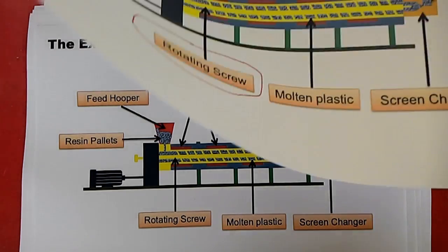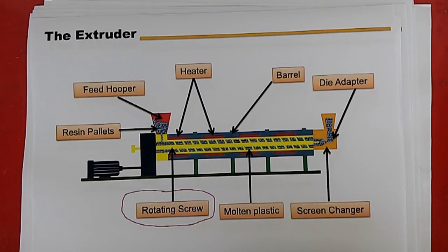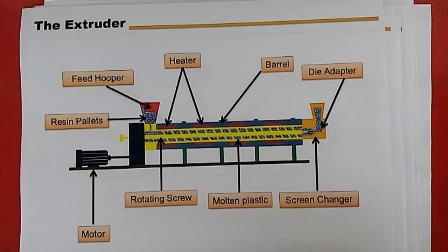The melt is pushed along by an extrusion screw. A motor-driven screw rotates within the hardened lining of the barrel. As the screw channel rotates, the screw flight forces the resin in the screw channel forward. The screw channel becomes more shallow and the resin is heated, compressed, melted, and mixed.